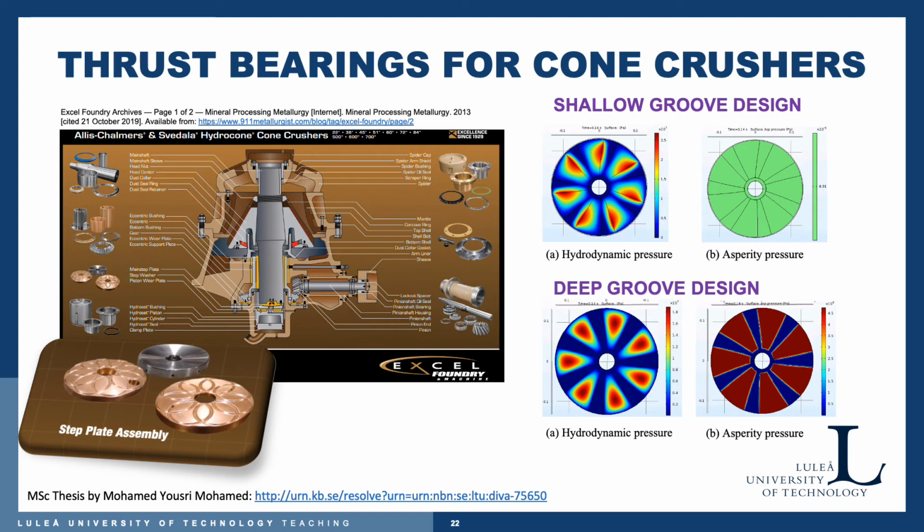In this case, the hydrodynamic pressure is perhaps not very well seen, but it's lower than in this case, because here the full load is supported by the hydrodynamic pressure and no load is supported by asperity pressure, but here there is a load partitioning between what is supported by the fluid and what is supported by direct contact.